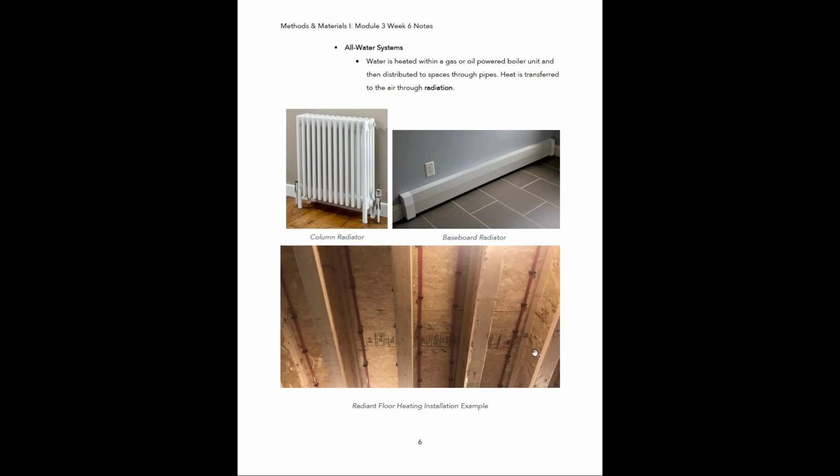These joists that we're seeing here, you should recognize these from the last module. So these are I-joists. These are engineered I-joists, okay, that have an OSB middle to them between a top and bottom chord. All right, so those are those engineered components that we talked about in the past. But the system that you see here, like I said, this is a radiant system. So as the water is traveling through these lines, the heat from it is being transferred to the subfloor, and it is then radiating into the space above it.